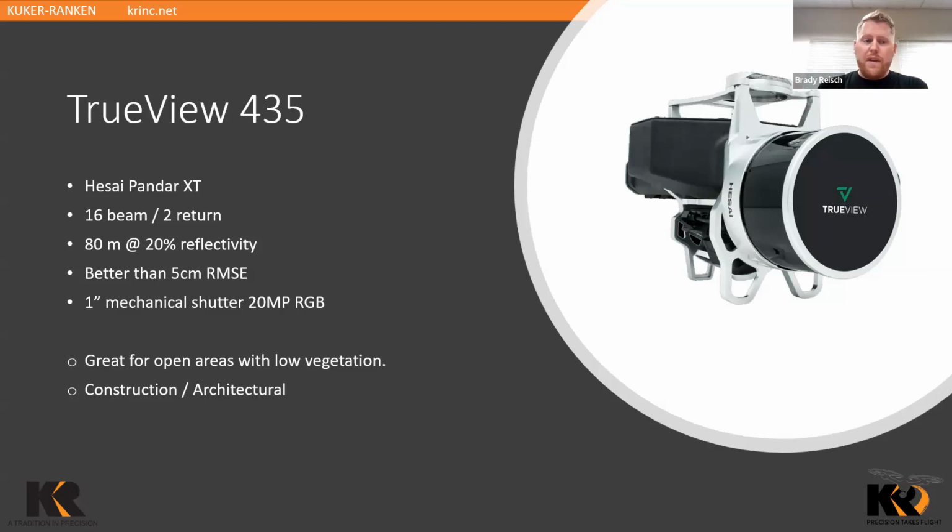So with the 435 system, we are looking at a better than 5 centimeter, basically a residual or error overall for your point cloud, which is actually really good. Now, 5 centimeters, what I will say is most of the GeoQ products under promise what you'll actually get.